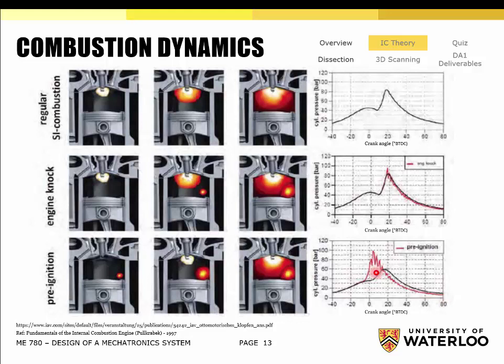So if you put gasoline inside a diesel engine, that's what you said? Both cases. So if you put gasoline inside a diesel engine, it won't actually run at all, because the auto ignition temperature of gasoline is too high, so it won't actually auto ignite, and you don't have spark plugs to ignite it, so you'll start the starter and it'll just make noise and not do anything. However, the other direction, if you put diesel inside a gasoline engine, most likely it will engine knock first and then it might pre-ignite after that.